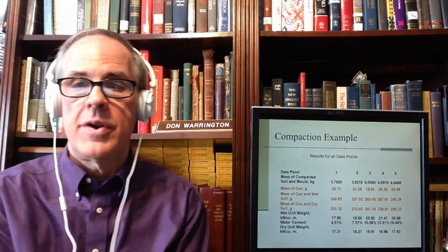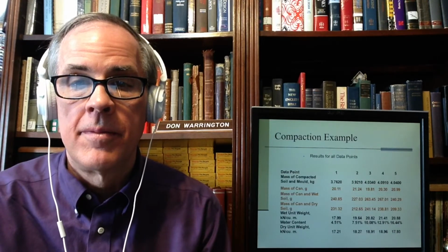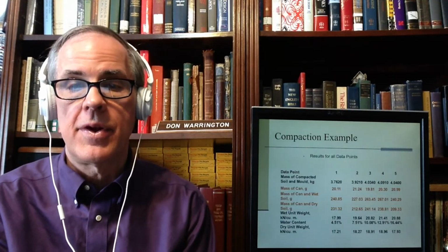So if I did it again for every soil sample, repeat, lather, rinse, repeat, it's the same procedure, I will end up with the mass of the compacted soil and mold, mass of the can, all that stuff, which I had before, and I calculate those and then I plot them.